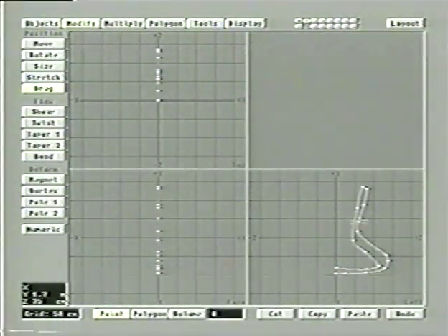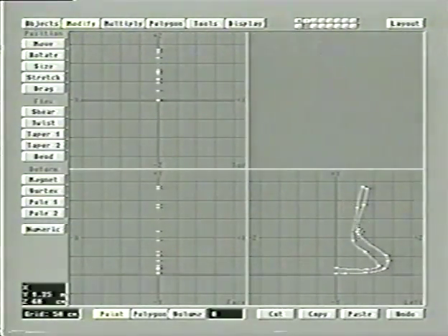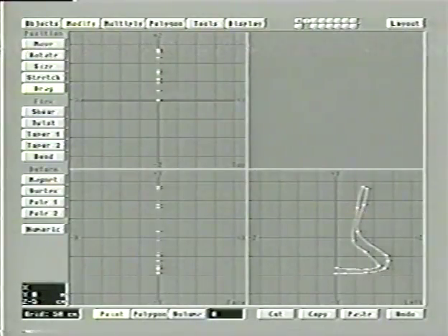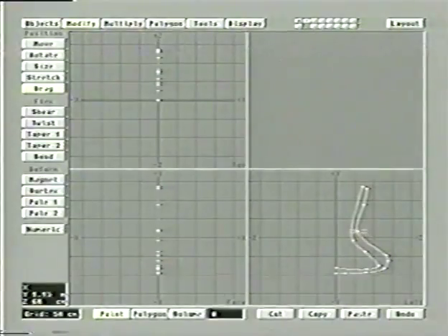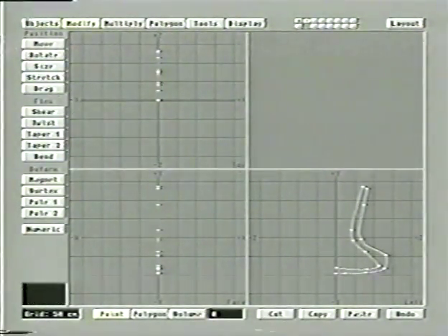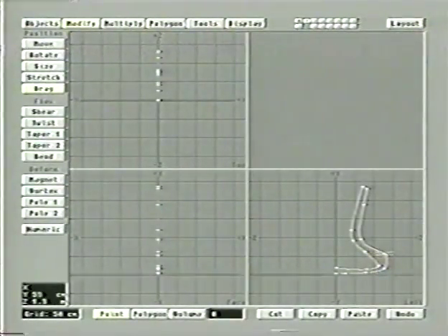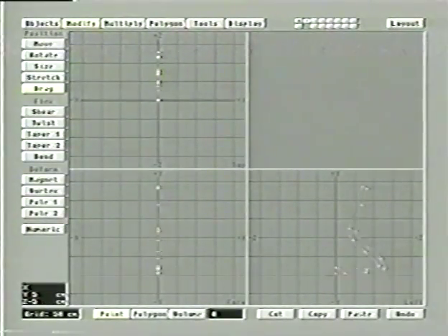By the way, this point here to me is extra. I'm going to go and select the point and cut it, because I don't feel I need that point there really to do the shape I'm trying to do. So since it's extraneous, I'll just get rid of it. Now, one thing is, you notice these are curves here. Got another point I want to get rid of here. Cut. These are actual curves, but when it lathes them, when it brings them around in 3 dimensions, they are turned into polygons. And do one thing up here. Close enough for a videotape right now. Let me just leave it like this.